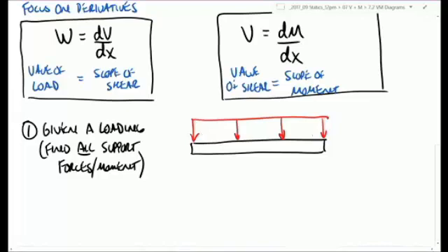In structural terms, they have both what's called live loads and also what's called dead loads. Dead loads aren't like zombies buried in the concrete or anything. They're just the fact that dead loads don't change. Dead loads are the weight of things that are bolted down like these desks, the weight of the flooring, the weight of the structural system, the weight of the HVAC system, the weight of the roof. Live loads are all of us, right, walking in and out. Other live loads are like wind and snow and things that can change over time.